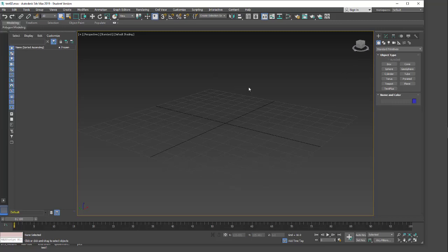Okay, so I'm going to make a box. This way it's just going to be clearer when I do a rotation. And I'm under my Create menu. I'm going to click on Box under Standard Primitives. And I want a cube. I'm going to do keyboard entry and then just set 12.